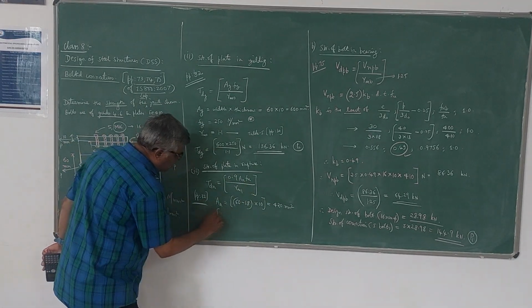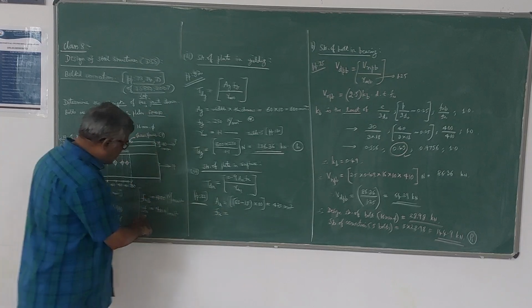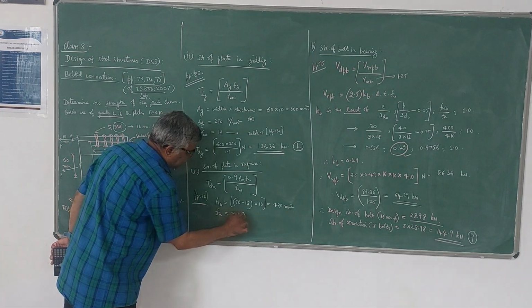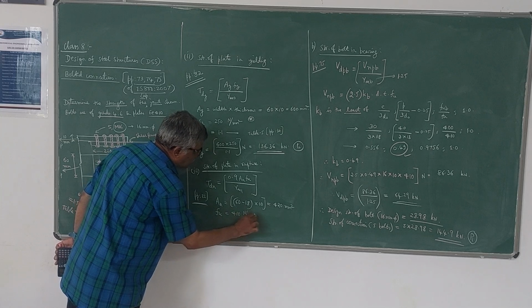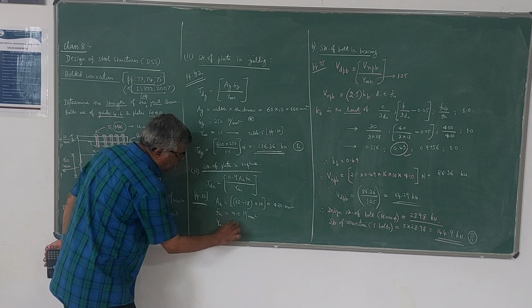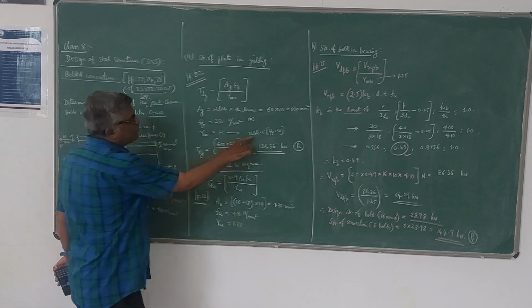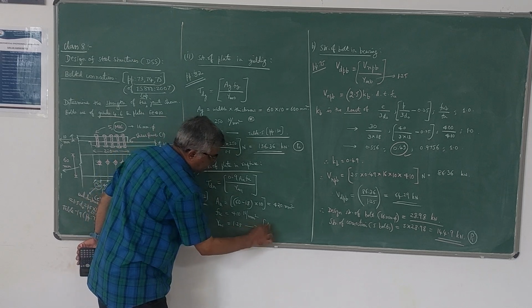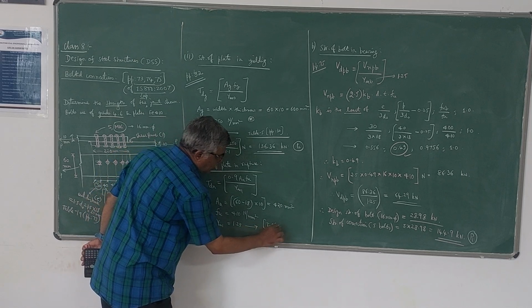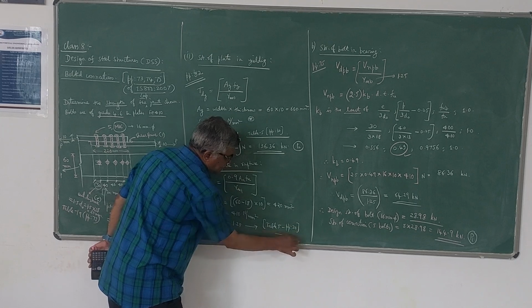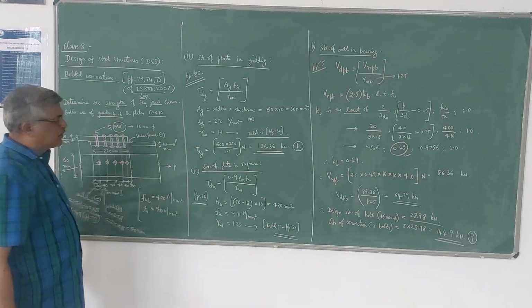So Fu value, as you know from the data, is 410. Fu value is 410 for the plate, Newton per mm square. Then gamma m1 once again is 1.25. It is obtained from once again the same table. All these gamma values are obtained from table 5 on page 30 of the code. So the partial safety factors we are going to get.